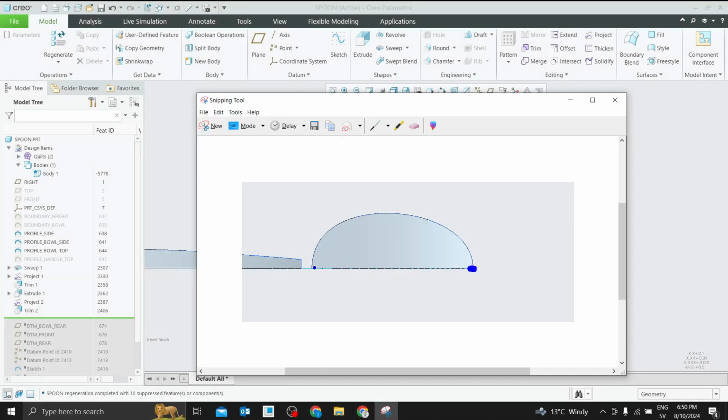These are called singularities. Here we have a plane that is already existing called the right plane. You select the right plane and this point here, and you pass a plane there. Then I put two planes here, at the same distance. I have used 8, 8. You can use 9, 9, or 10, 10, depending on the accuracy of your model. Then on these two planes, I have created a curve.